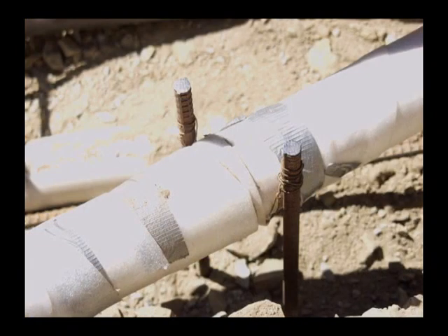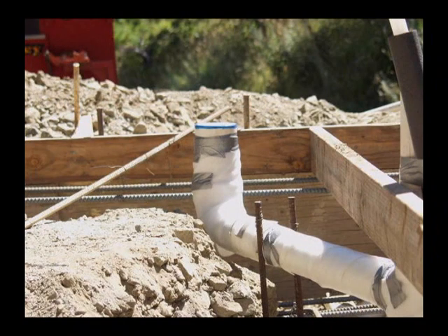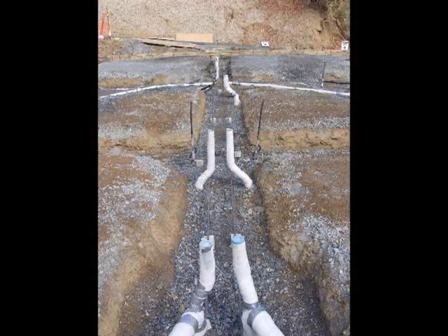Same thing if you want to hold something off the ground. Here's a sewage line we needed to hold up off the ground. We've got some rebar with a wire harness just sitting across to keep it in place. The toilet flange you want to have just above the grade of the concrete. Again, you'll be able to cut that out flush once the concrete has been poured and do the finished concrete at that time. So once all your sewage lines and water lines are in place, you can backfill around them, and then you're ready to create your grid and pour your concrete.